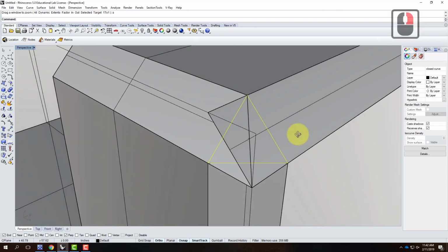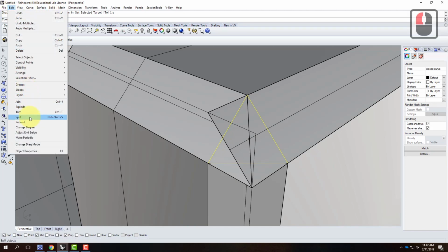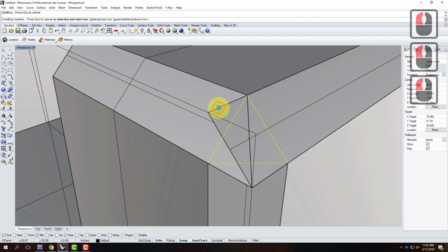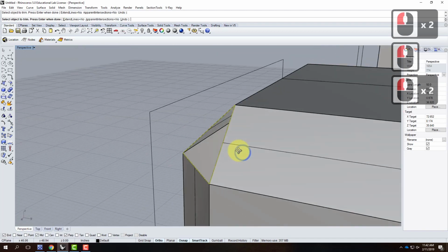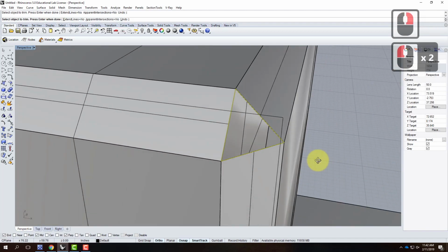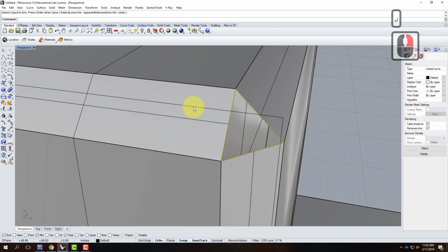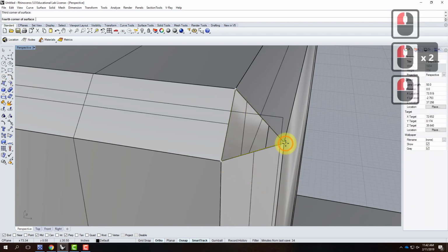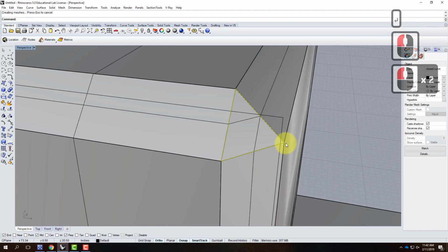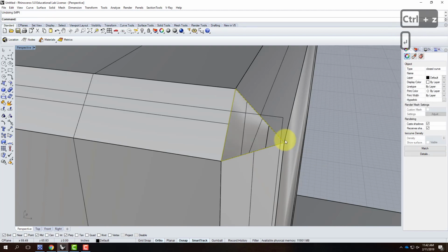Perfect. Time to go ahead and trim. I'll go up to use my trim tool, or I'll go to edit and then trim. Or of course I could type trim. And I'll get rid of these pieces that are extra. And there's that. When I'm done, I'll press enter, and then it's time to fill this piece in. So I'll go back up to my surface from 3 or 4 corner points, and I'll do it 1, 2, 3, and press enter.